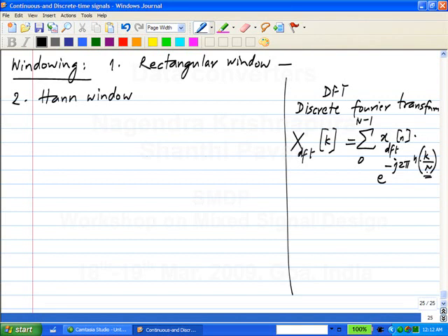And normally you hear the term FFT, which is the fast Fourier transform. Basically it's a way of calculating the discrete Fourier transform in a fast way, computationally. So although you say taking an FFT, you are really taking a DFT, and there is some algorithm which makes it fast. Now how fast it is depends on N. And the most optimal values are integer powers of 2, it turns out.